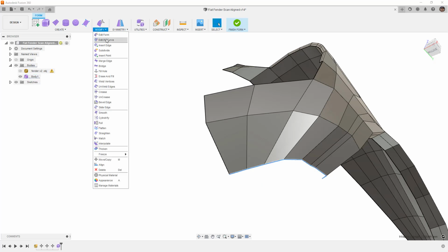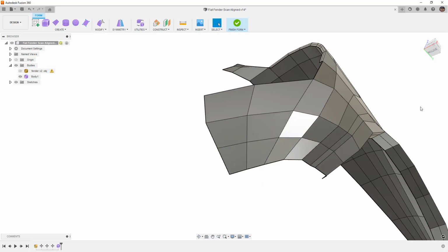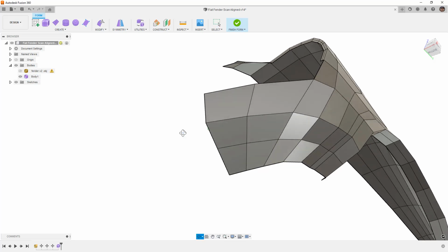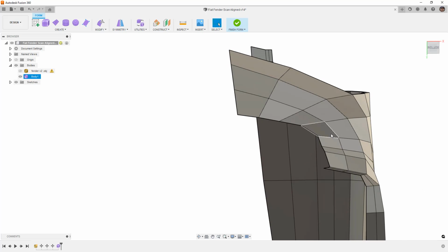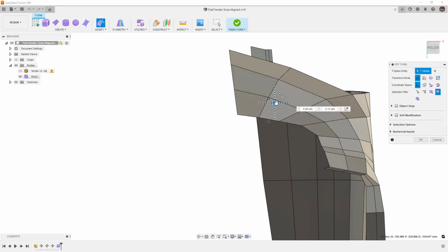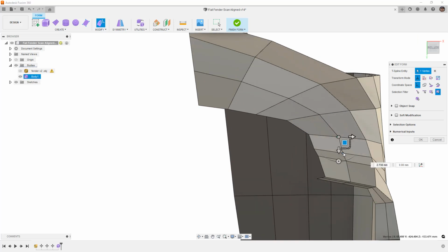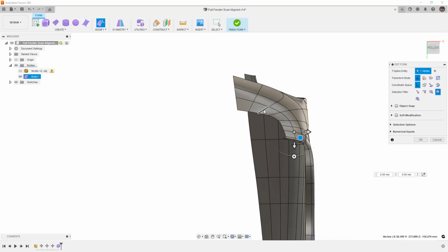I'm going to double click on this bottom edge, and I'm going to insert one vertically. Again, that is going to be a problem for geometry just to have that inserted. So I'm going to manipulate it slightly. I'm just going to move these points out ever so slightly to make sure that it's not flat. Kind of move them out roughly normal to the direction of their curvature. And we'll come back and fix everything after that. So smooth display.